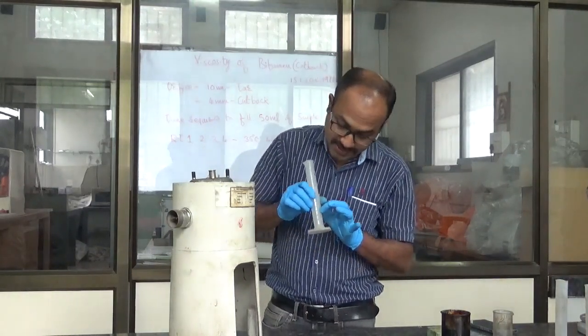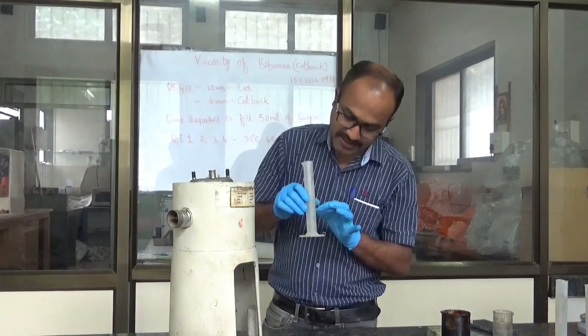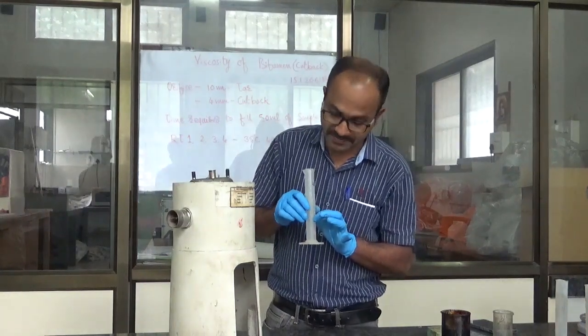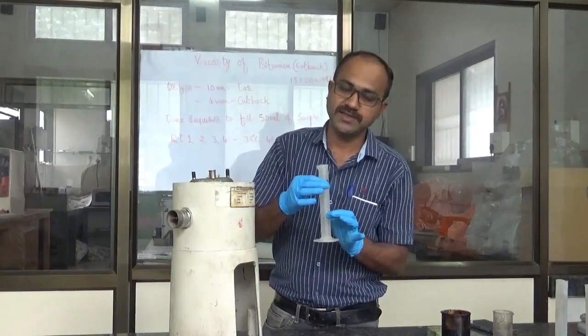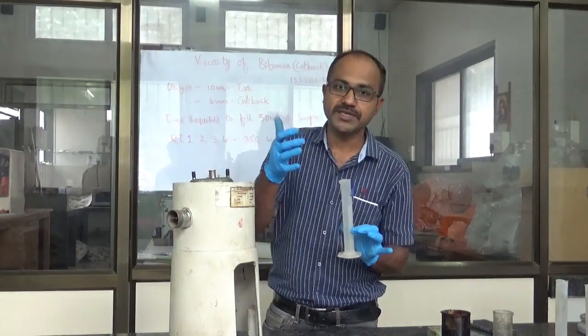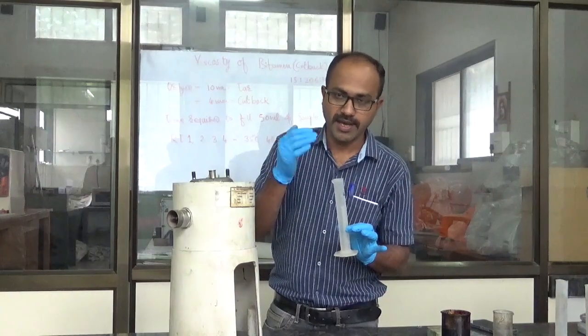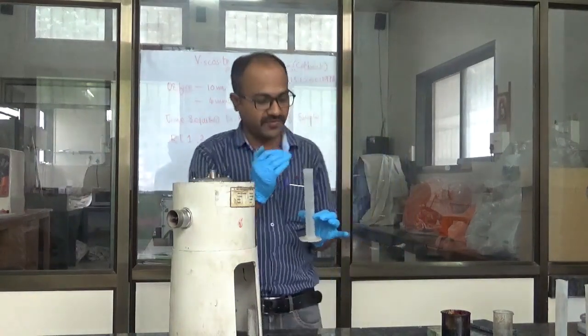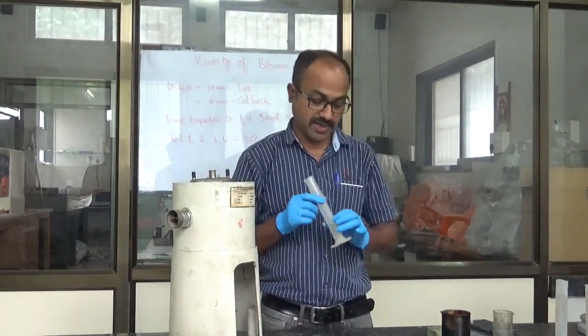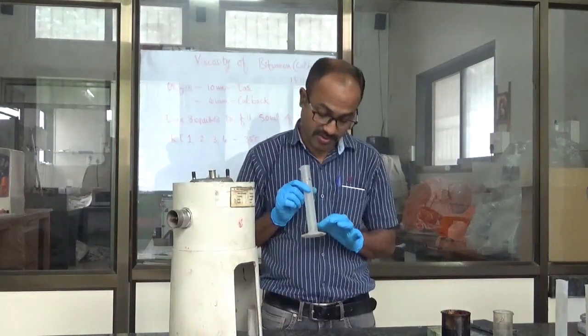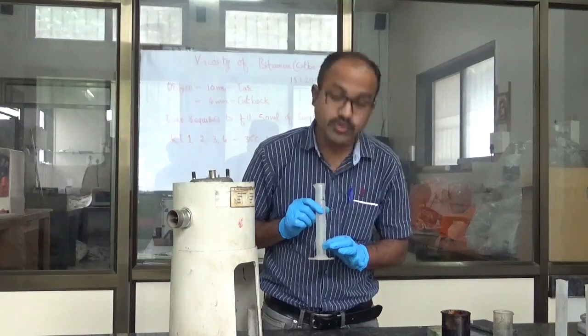Once my sample reaches 25 ml, you can start your stopwatch, and once it fills up to 75 ml, you can stop your stopwatch. The time we get gives you the viscosity of the sample. Why are we adding the mineral oil or the soft soap solution?